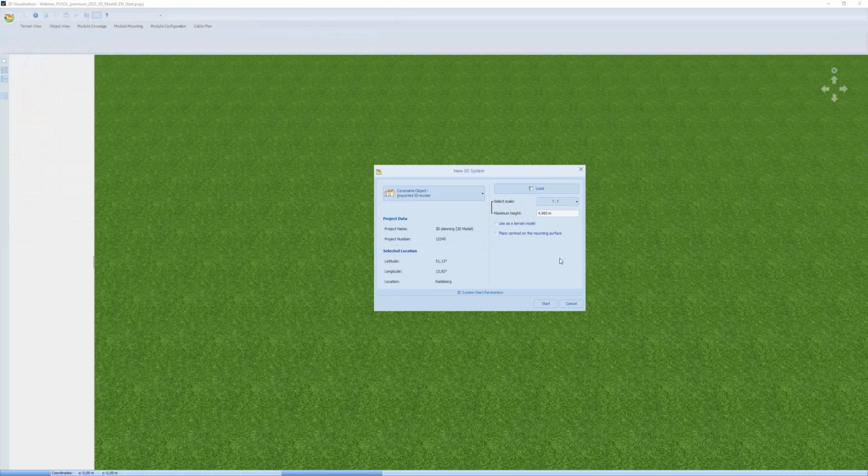But sometimes, depending on the CAD program, the scale is probably placed in another section of the file, and PVSol cannot find it, or it's not the correct scale. Then you can scale the whole 3D model by adjusting the height. In the next picture, we will see there's also a tutorial available to us for this and how this can be done. Then we have two options.